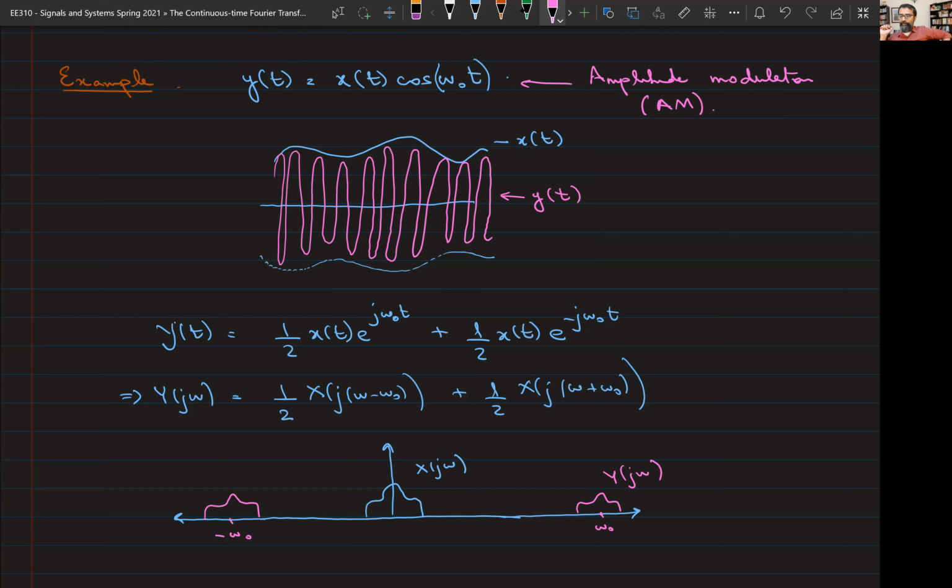This has to do with electromagnetics, right? So it turns out, you may or may not have come across this, the antenna size you need to transmit a radio signal depends on your wavelength, or on the frequency. The larger the frequency, the smaller the antenna size required, and vice versa. So to transmit baseband you need a very, very large antenna.